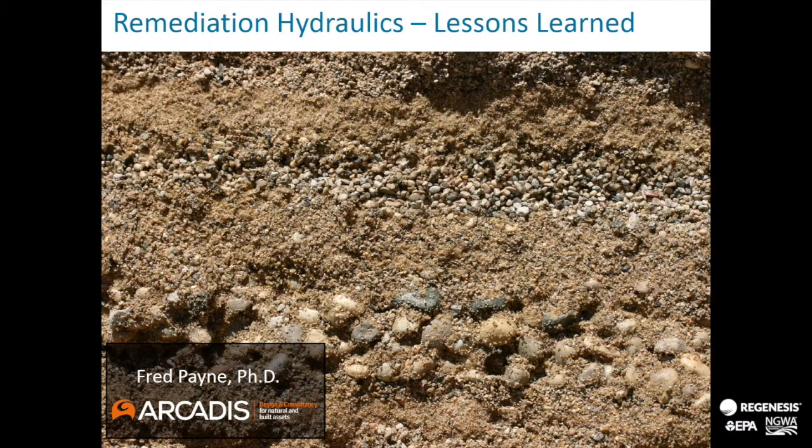And how would we detect a formation like this with our classic geology tools? We've got some pea stone here that's very well sorted, very clean, and in this section is where 99% of the flow is going to go. We've got some moderately permeable sands here, and then we've got these stones, which, if you think about it, wow, those are big stones, they must be highly conductive, but what you really have is medium sand with 80% blockage. So it's actually the lowest permeability section of that profile.